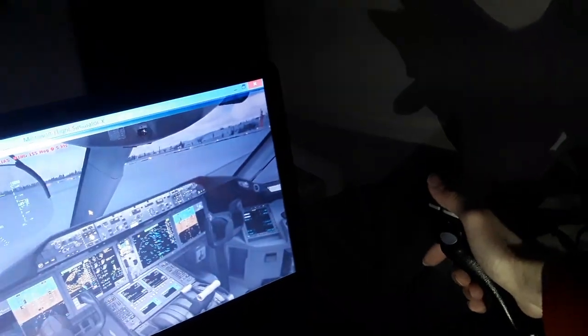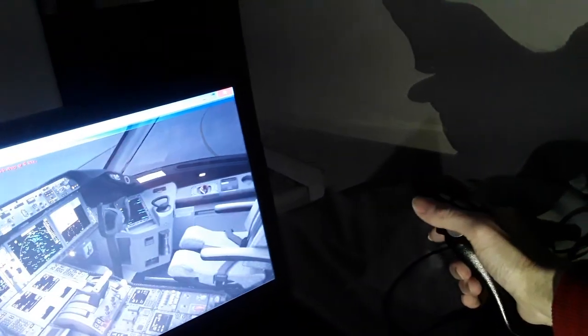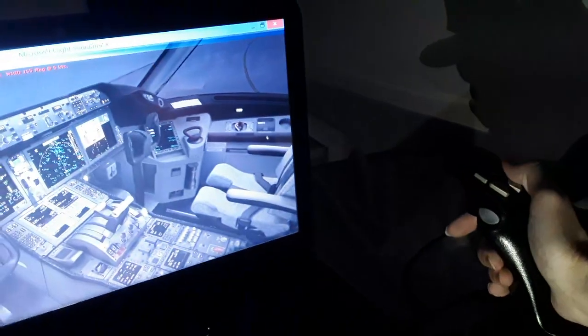Boeing has similar features. We have also the alpha protection, the 1G stall, anti-stall system for the 1G angle of attack. When the aircraft reaches the angle of stall, it applies full takeoff thrust in the Airbus and locks the angle of attack. So we have other features, other speed protections. I will show you one more view of the flight controls of the Boeing 787 right now, and then I will set up the flight control computers, the flight management computer for this flight.